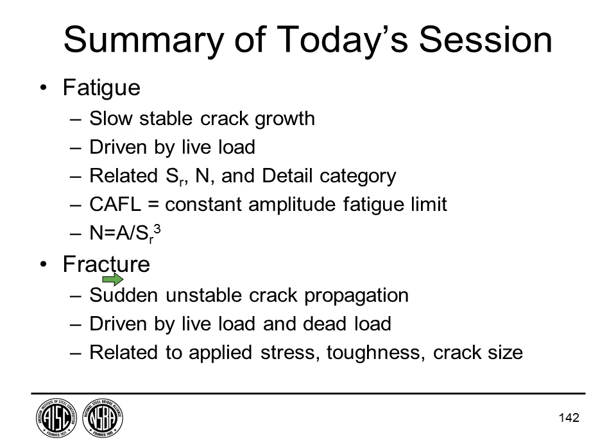So I guess a quick summary. Fatigue, remember, is slow and stable. You can inspect for that. It drives slow. If I take the load away, cracking will stop. We had detail categories, right? We had numbers of trucks that drive that, and the stress range.